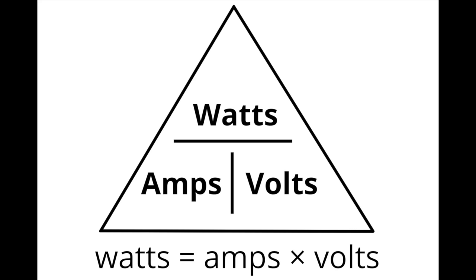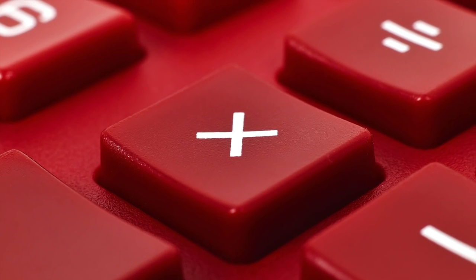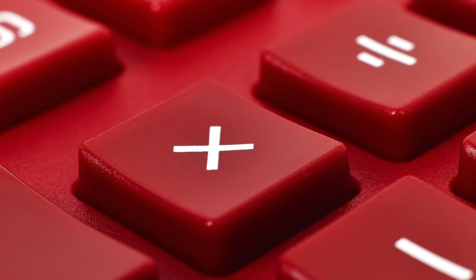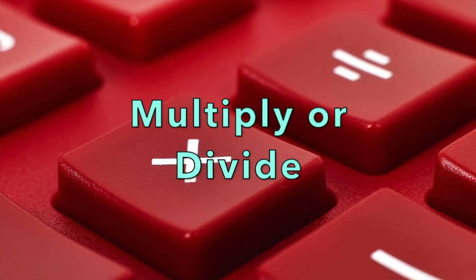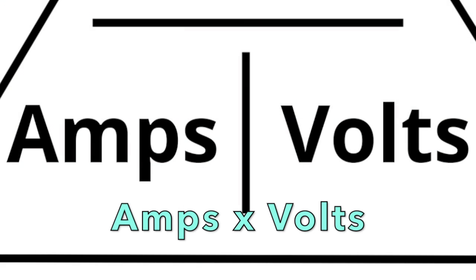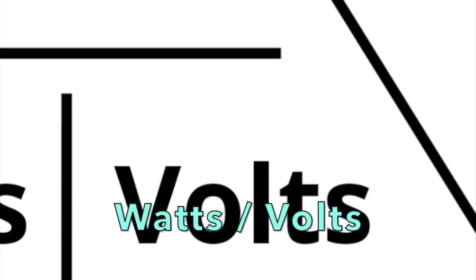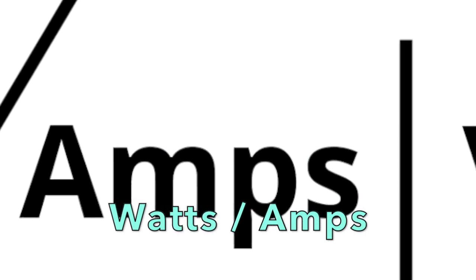This formula can be used to calculate the energy usage for simple resistance loads. If 2 of the characteristics are known, the third one can be calculated. With the watt visual graphic covering up the characteristic that is being requested, its position determines if a person should multiply or divide. When solving for watts, amps and volts are side by side, so multiply amps times volts. If solving for amps, watts is divided by volts. When solving for volts, watts is divided by amps.